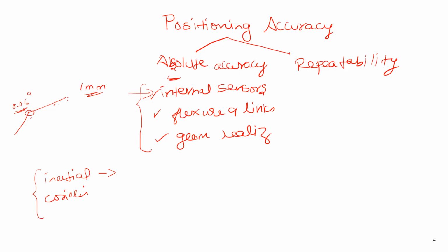So the inertial forces will vary with the square of the length of the link, and also the serial robots will be experiencing frictional forces, but the frictional forces are unaffected by the dimension. So we cannot design a serial robot simply by scaling down a larger version, right? When you do the scaling down, the inertial forces are decreased, but the frictional forces remain unchanged.